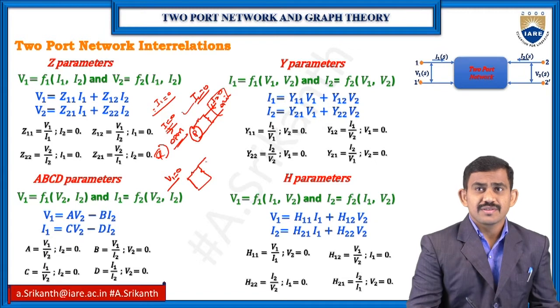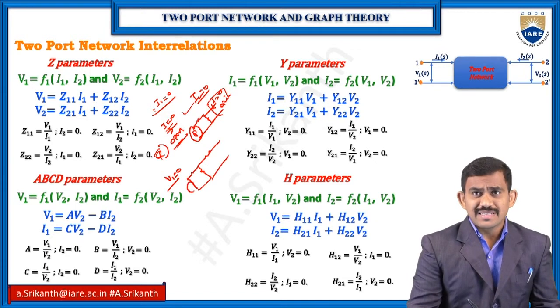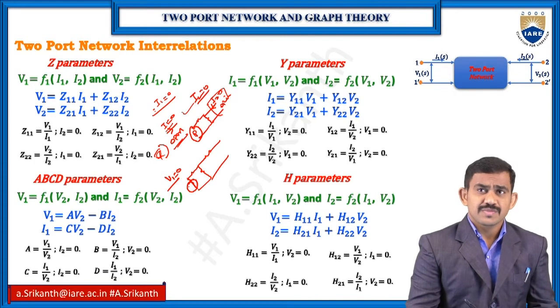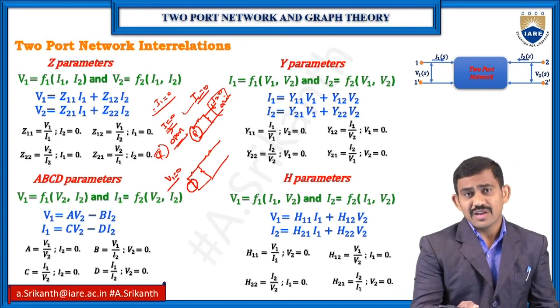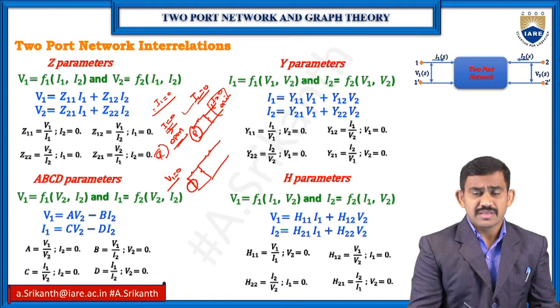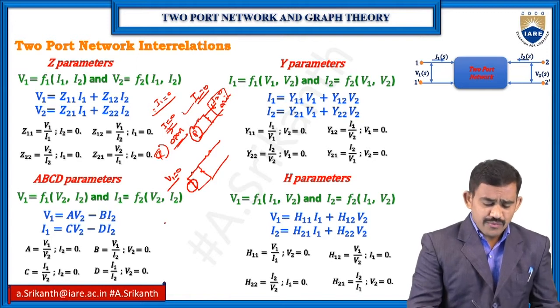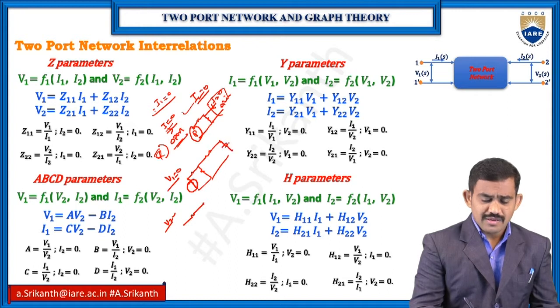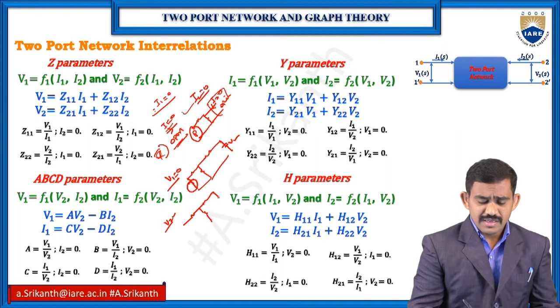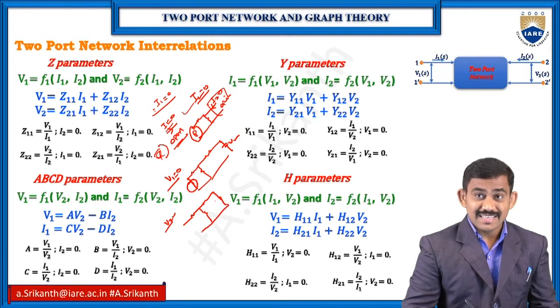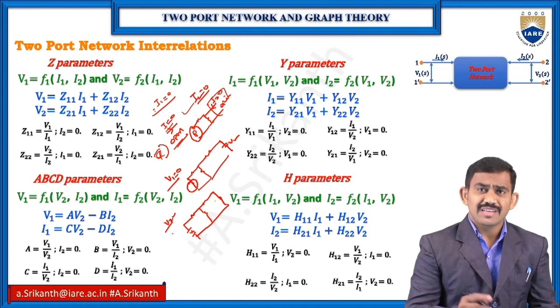So for any circuit, here you have a T-type network. The primary side is short circuit, and find out which value you want: I1 value, I2 value and V2 value, the remaining values. And same thing, V2 equal 0 means, in the same T network, the second side is short circuit. Here I have a V1 value. Again, find out the remaining values.